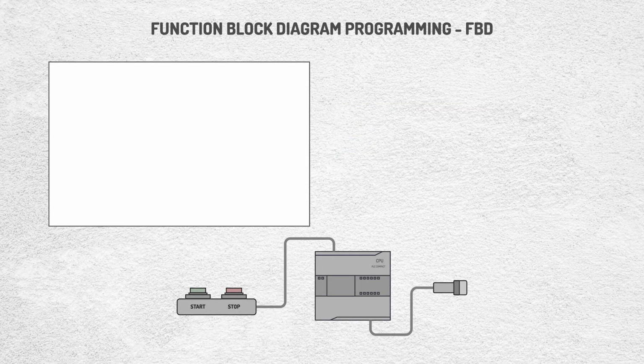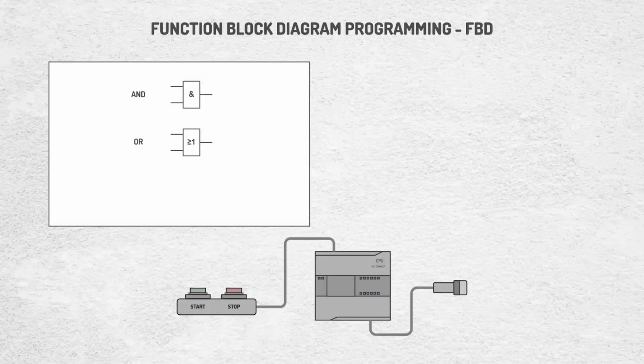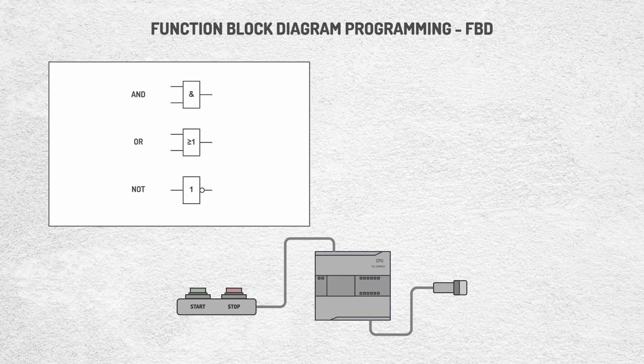Now we will see the same example using the same variables but implemented in another graphical language, function block diagram. This language is based on function logic. Its foundation comes from Boolean logic, the same used in digital circuits, where each block represents a function, for example, an AND gate, an OR, or a timer. This type of language is very visual and intuitive since it allows building the program simply by connecting blocks that process input and output signals.